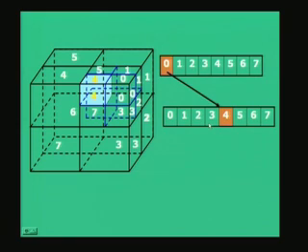Now, it may be possible that only a part of that 4th node is occupied, not the full one. So, in that case, you might have to again break the 4th node into 8 equal sub volumes, similarly with the 3rd node, or if you feel that there is some occupancy by solid objects, by planes or whatever it is, in the 3rd sub volume at the second level of decomposition, you need to break it further and so on. So, this is the explanation which shows how to build up octrees for representing a solid.